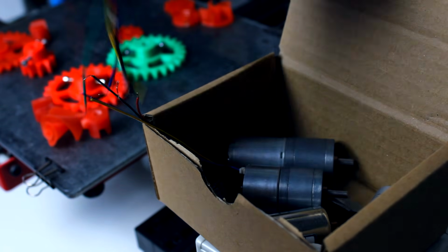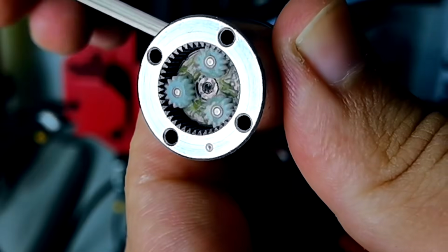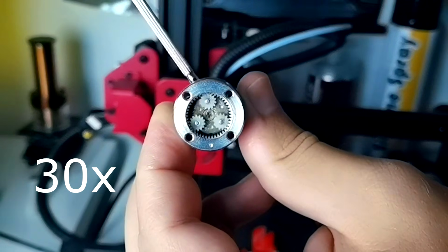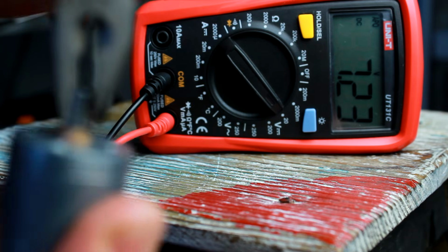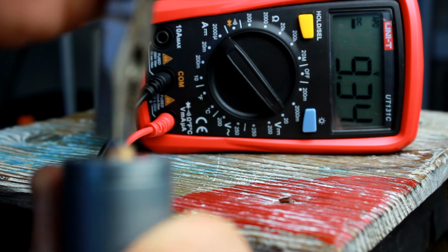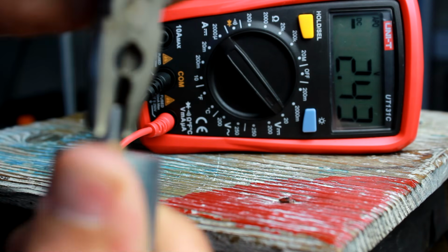So if I wanted to use a DC motor as a generator, I needed to find a way to increase the output speed. So I used gears. To solve my problem, I bought some DC motors with planetary gearboxes with ratios of 1 to 30. That means 30 times more speed. Even turning them slowly was getting me over 3 volts. It seemed like I found my solution, but I didn't.